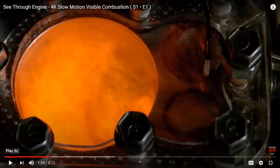Okay, so I'm no engine expert, but I believe what we're looking at is a single cylinder. You can see the piston moving up and down inside it. These would be the valves, the intake and exhaust valves. You can see them going up and down at the appropriate time. But what I'd like to draw your attention to is the fact that the combustion of the gasoline doesn't actually happen during a perfectly isochoric process, but the piston doesn't move down by much before the combustion is basically finished. So the introduction of that heat QH can be pretty well modeled as an isochoric process.